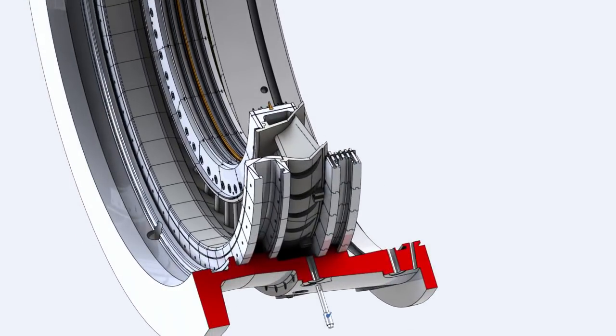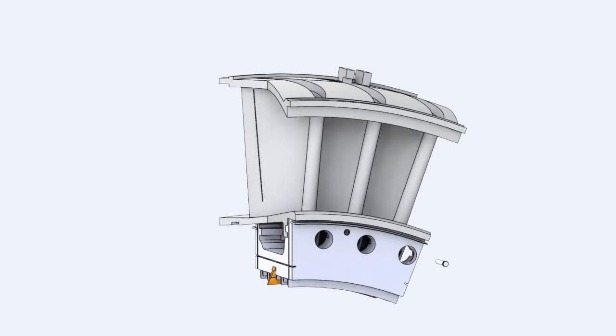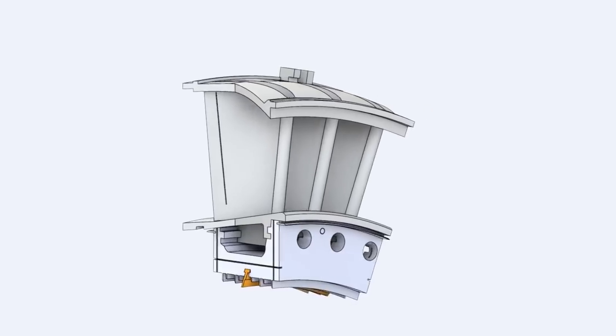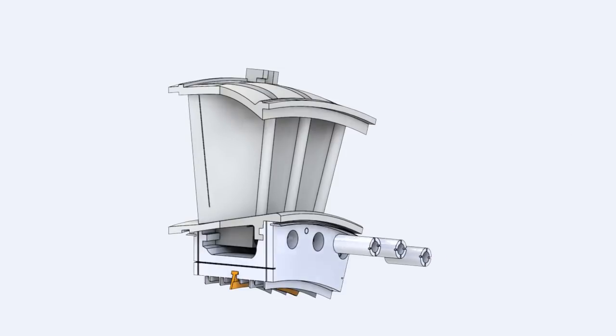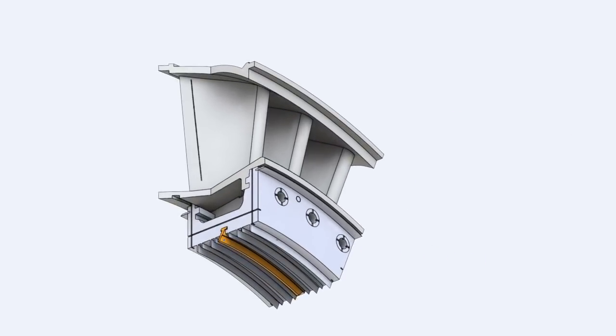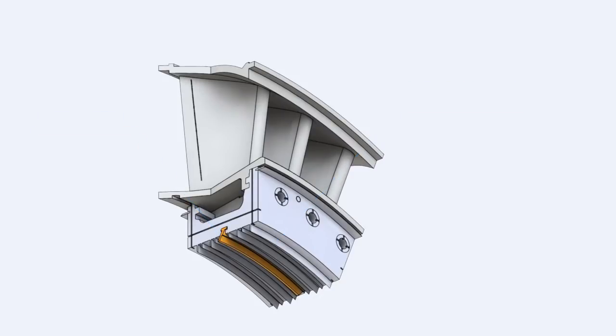The nozzle segments are held on the circumferential position by radial pins from the turbine shell into axial slots on the nozzle outer sidewalls. Annular curved segments are attached to the inner sidewall of the nozzle. These segments are called the diaphragms. Each diaphragm is secured to the nozzle by a pin. These diaphragm segments prevent hot gases leakage past the inner sidewall of the nozzle and the rotor. A high-low labyrinth seal is machined on the diaphragm inside diameter. These seals mate with opposite sealing lands on the turbine rotor spacer.